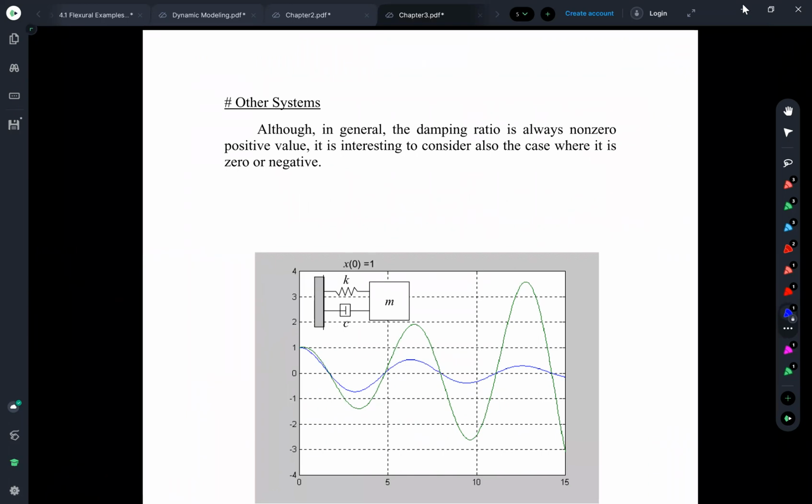And this is another system, number 4, maybe 3.4, where you have a negative damping. If you have the negative damping, during the vibration you gain larger and larger displacement with time. And the system is unstable, right? You can imagine that if you let the system go for a certain time, it will destroy itself because the displacement becomes infinity. And we don't really have this.